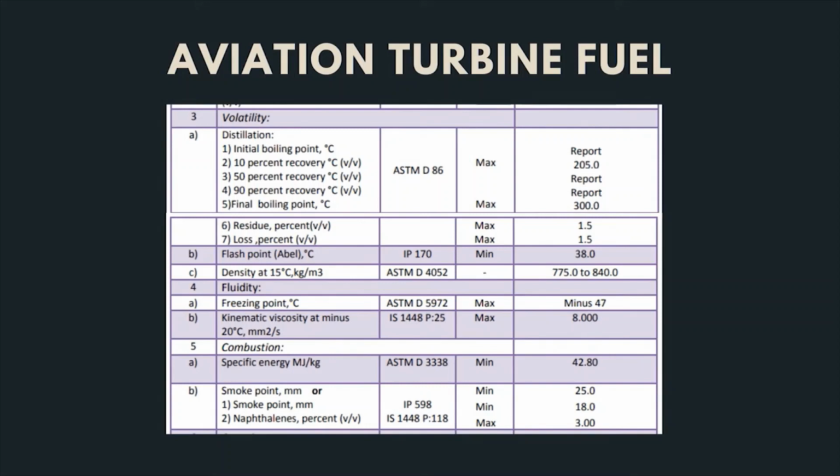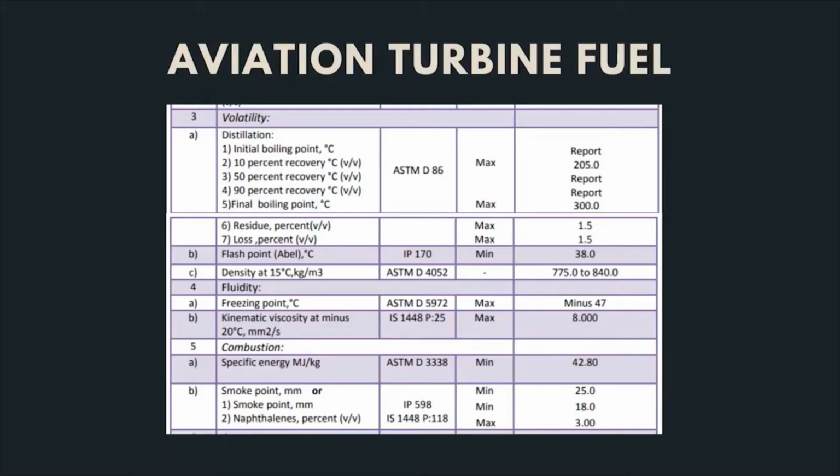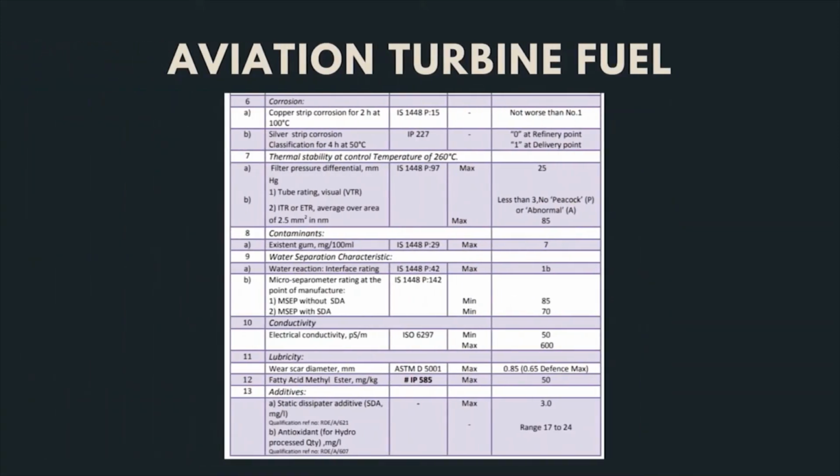Freezing point is an important test for aviation turbine fuel, because when the flight is flying at an altitude of more than 30,000 feet, at that temperature this fuel should not freeze. Because of that, the freezing point is very important, and the freezing point defined in India is minus 47 degrees centigrade.